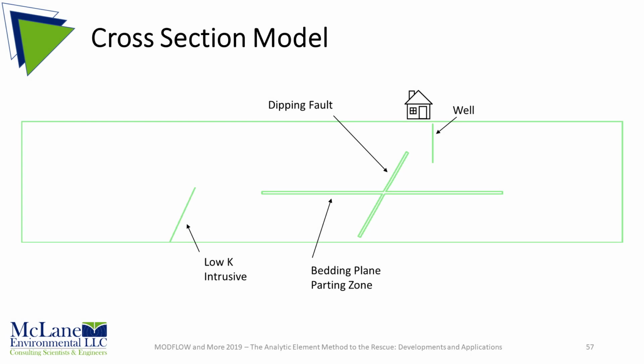For this demonstration, we suppose that geologic investigations have shown the presence of certain planar features in the aquifer, including a steep vertical angle low permeability diabase dike, represented by a no-flow barrier line element, a horizontal zone of fracturing along bedding plane partings, represented by a long, narrow hydraulic conductivity heterogeneity, and a steeply dipping cross-cutting transmissive fault zone, also represented by a long, narrow hydraulic conductivity heterogeneity. Notice how the bedding plane heterogeneity and dipping fault zone heterogeneity have been joined to transmit flow between them.